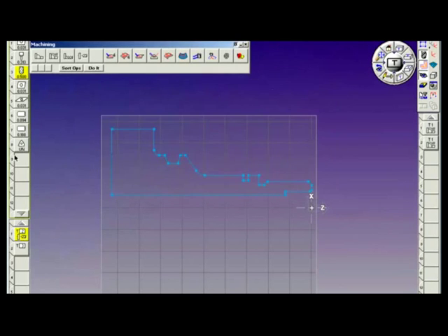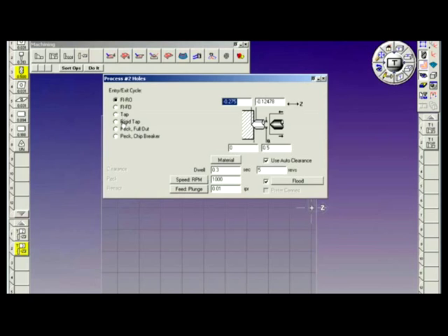Okay. Bring the holes process down on process tile number 2. This particular tool is going to be a peck with a full out. The clearance 50 thousandths, peck 0.5. The peck defaults to the diameter of the tool. 0 dwell.